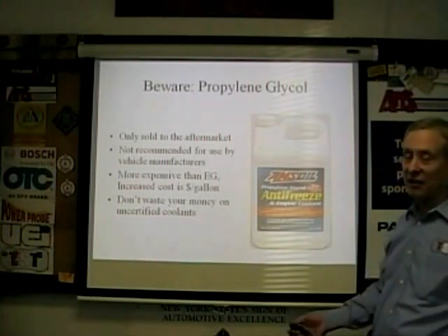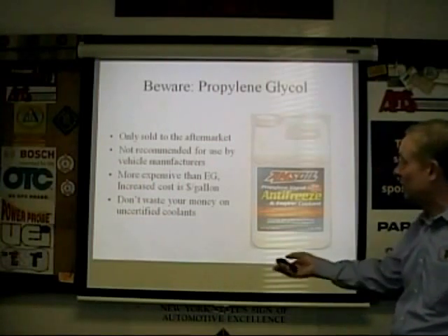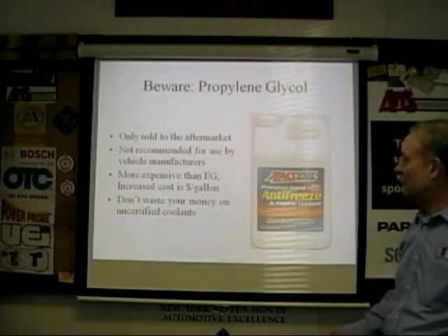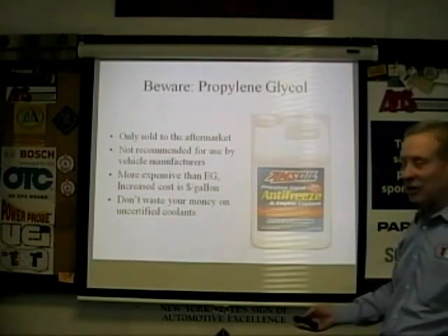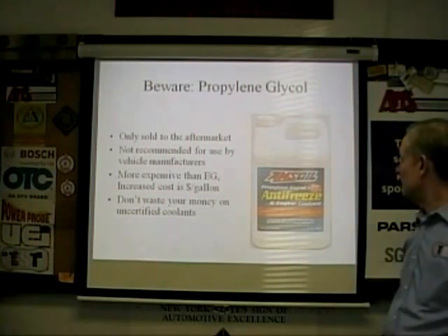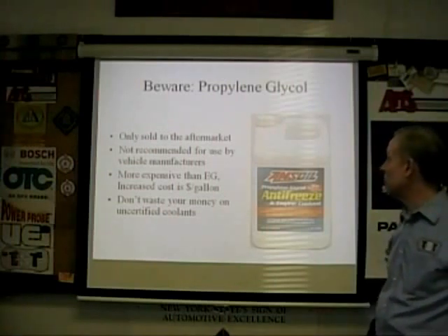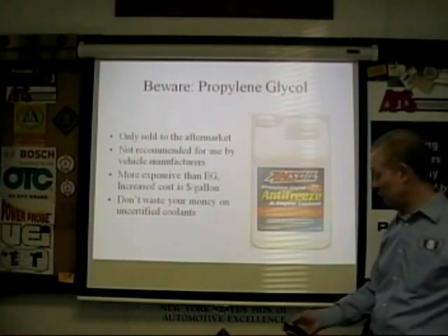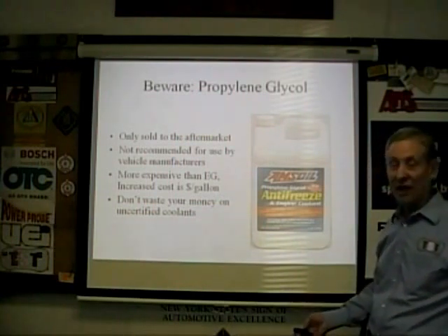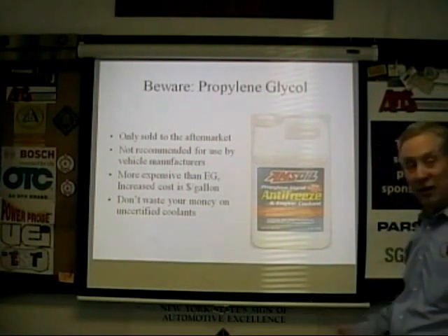Unfortunately, it does not handle the extreme heats of automotive engines, and it's really not a good idea. It's not recommended by any manufacturer, as you can see here. It's more expensive as well. There's really no good reason to put it in a car. You're just a test pilot. Even though it's AMSOIL, an aftermarket brand of a lot of chemicals and oils, not a good idea. This is a case where you don't believe the salesman. I have it in my wood-burning boiler at home, but it's not for a car.